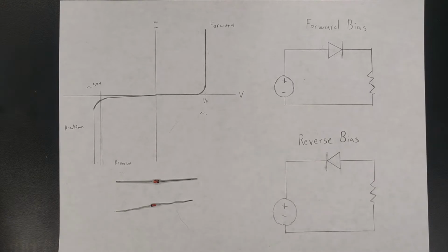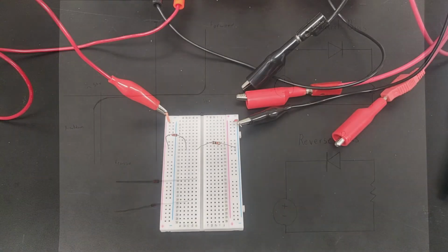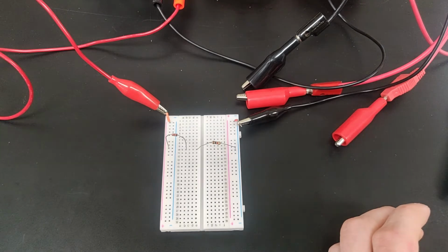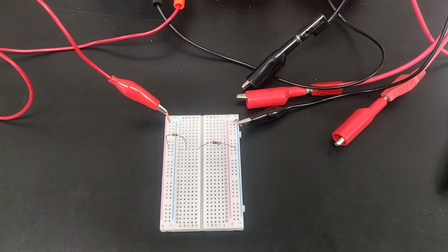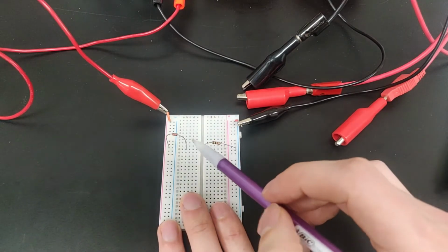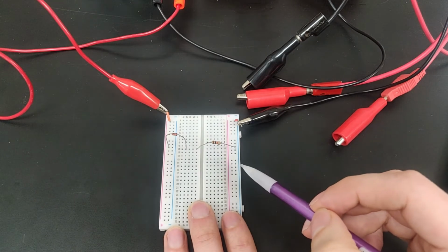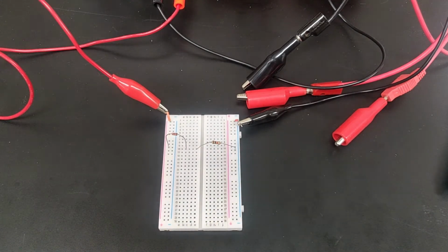I think that's it. Let's start the experiment. Okay, so this is part B of experiment 3, that diode section that I didn't go over in the previous video. So I've combined that latter section and all of experiment 4 into one. And in this part B, it's fairly straightforward. We are just recreating that characteristic plot of the voltage versus the current of our signal diode. So we're going to be making several measurements, both in the forward bias and reverse bias orientations, so that we can recreate those plots for our specific components here.